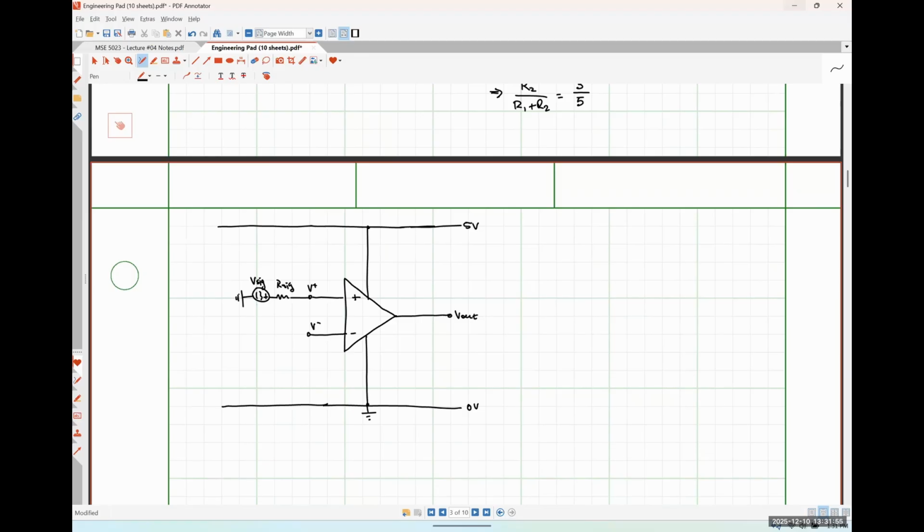And now I'm going to set up that voltage divider network. So that's just going to be connected between here and here, where this node point is essentially establishing our reference voltage. This is the resistor R1, and here is the resistor R2.